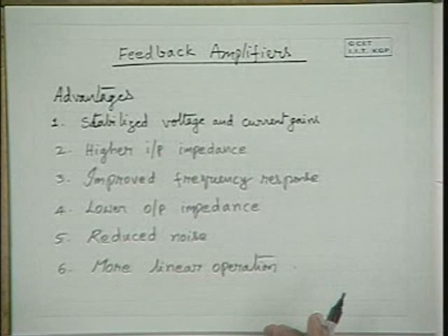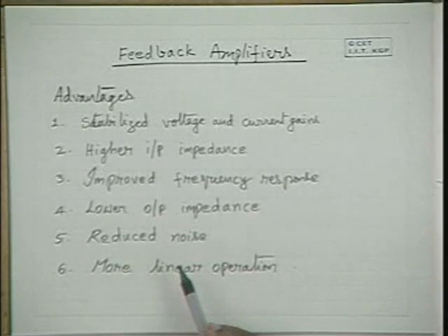A transistor is a nonlinear device, and for small signals it acts like a linear device. Please note that even for small signals, if you really examine it, it has nonlinear characteristics. The only consideration is that the nonlinearity is very small. However, in certain applications that nonlinearity matters, and if you want to improve the linearity, we can do so by using the feedback concept in the amplifier circuit.